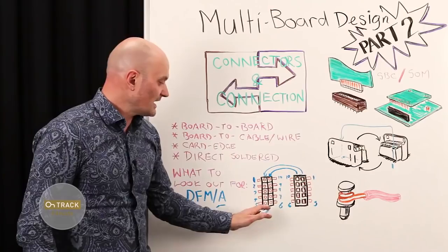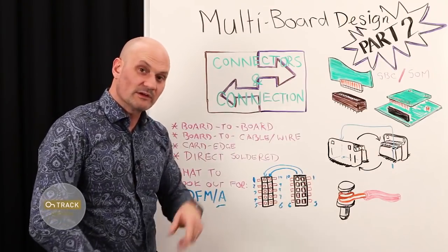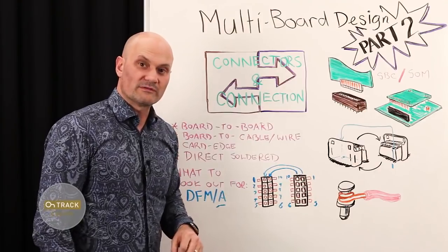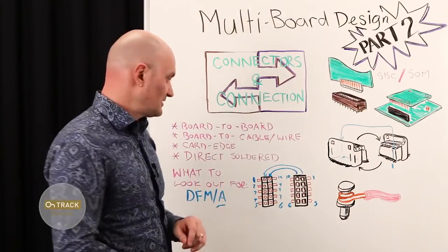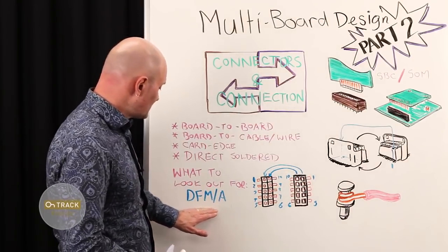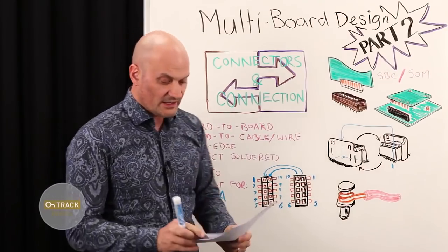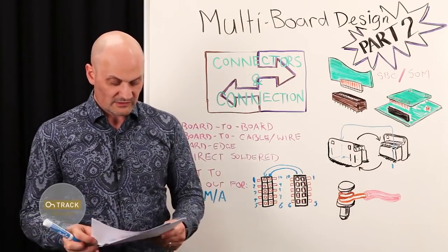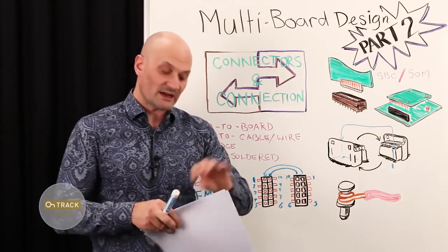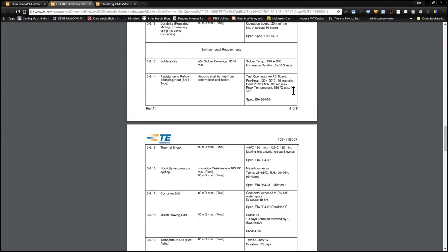And so again, this comes down to your CAD library, and you need to number these correctly with forethought of how these are actually going to be used in a multi-board assembly. On the subject still of design for assembly, one more issue to look out for, and again this is something that should be specified in the manufacturer data sheet, and that is operating temperature range.